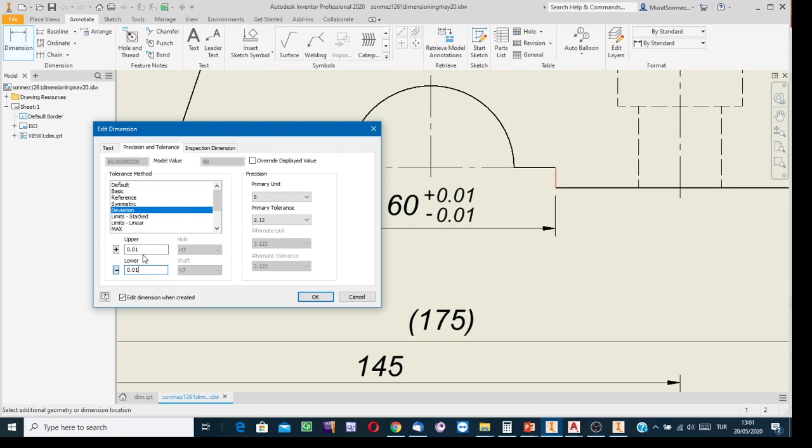Okay. Although I typed 3 figures, why do I still see 2 figures? Because you see here the precision, well, for the deviation values the automatically selected number of figures is 2. If you need to show not 2 but 3 figures, then select this option and then start seeing the deviation with the necessary figures. Okay.